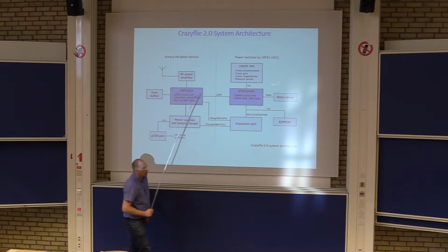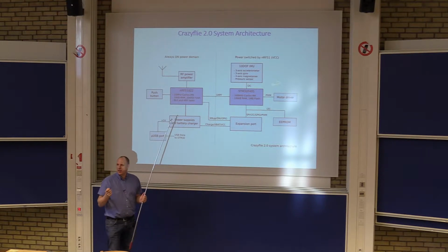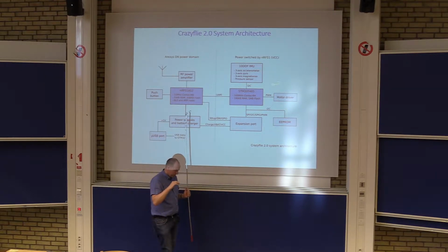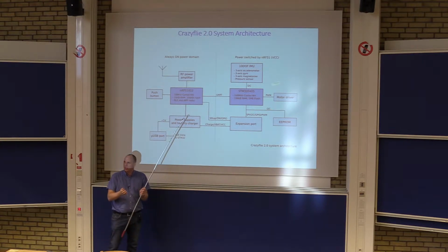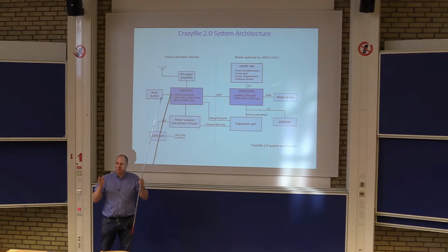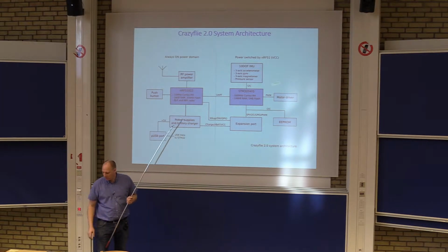So inside the IMU, you will have an analog to digital conversion. The forces that the accelerometer senses and the angular velocity of the gyro are turned into a voltage that is then transformed into a number by the analog to digital conversion. And that can be done with different kinds of resolutions, depending on how many bits will be used to represent the force or the angular velocity.